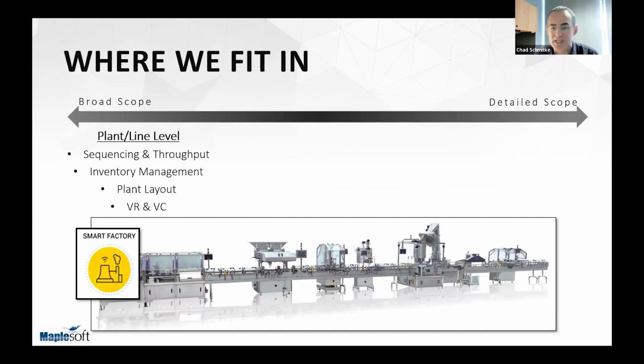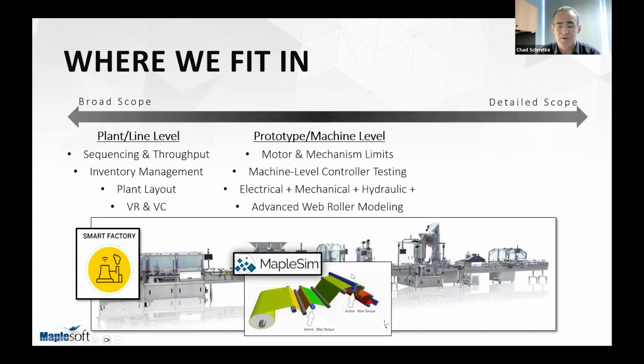When people talk about simulation there, they're often concerned with moving things from machine to machine down the line. They're looking at whether the eyes are picking up the product, whether the gate opens at the right time, and when the web is cut, whether the machine or robot that takes that roll and moves it somewhere else has all that timing working and in place. They're looking at discrete events, not at continuous dynamics, is what I would say in the simulation world.